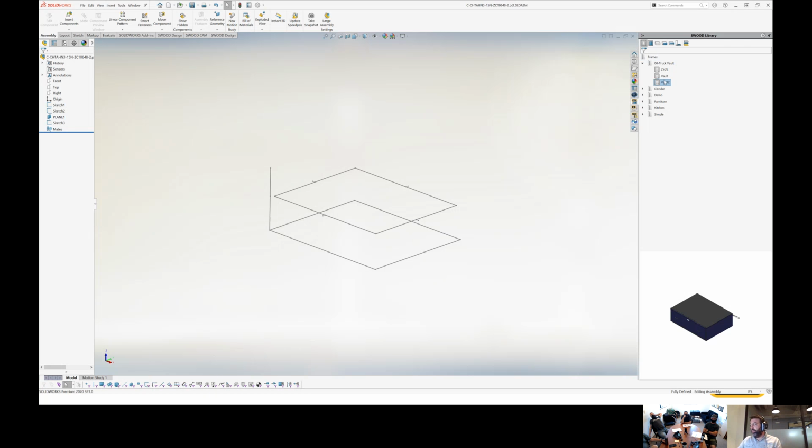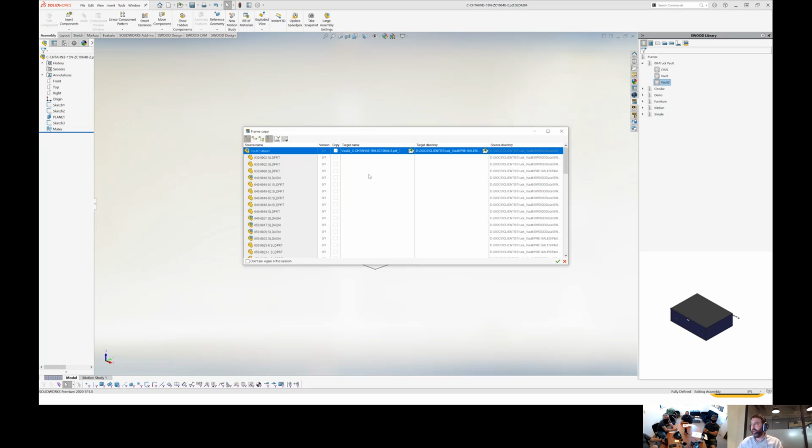And now I can use my vault here, or I can use any kind of vault I will have created in my library. And I will just right click, insert copy. So every time we do that here, we are duplicating all the panels. All the hardware are not copied. You can see that here. And for example, I can just rename B1, for example.